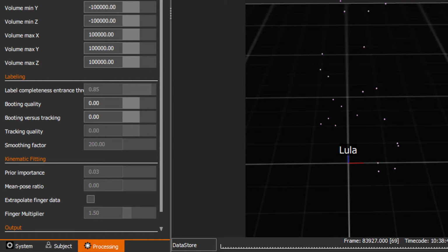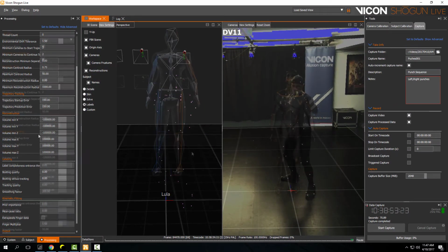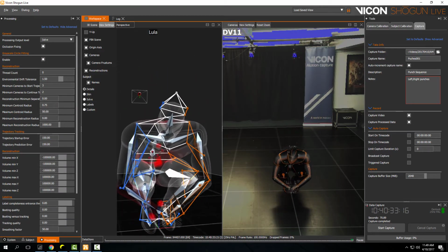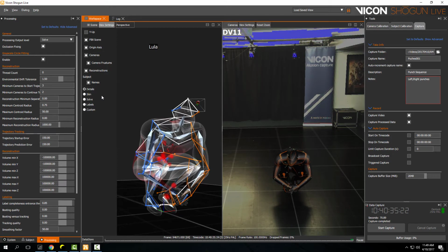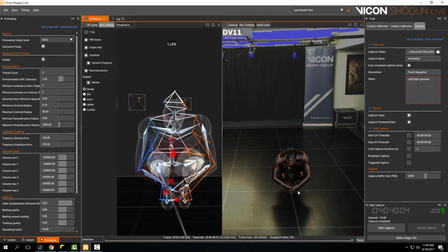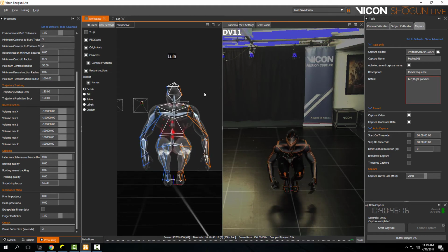If the value is too high and you have fast moving data with gaps, you may see the data become spongy during fills. Anything between 25 to 200 can be used, with the lower values offering tighter fills at the expense of potential mislabels. There is also an option for occlusion fixing. This is recommended to be on as it fills in any missing marker data during heavily occluded actions, as visible here. Traditionally the real-time would collapse during these actions, but thanks to occlusion fixing they are now not only achievable, but also maintain the original movement of the performer.